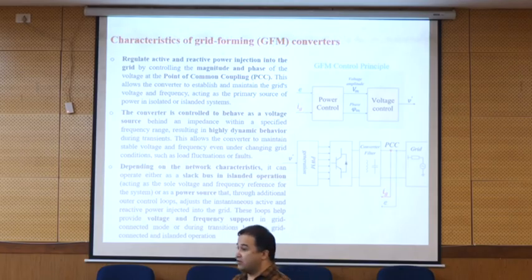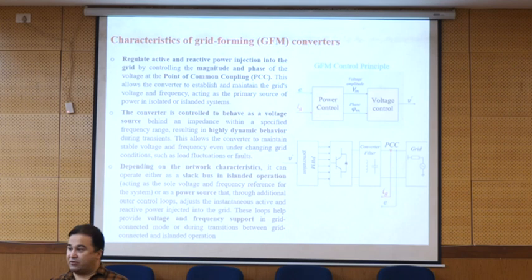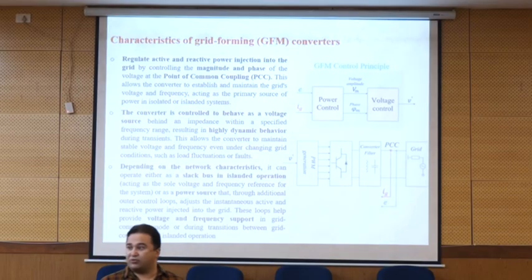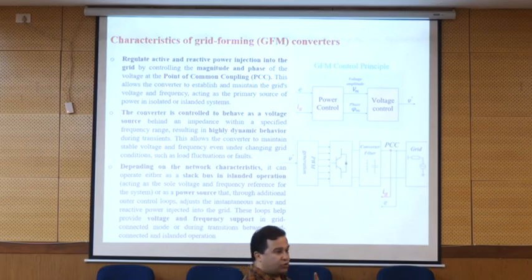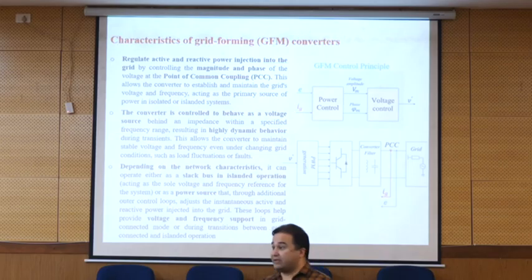Basically any component, it can be a transformer, it can be a converter, it can be anything, but you need to follow the grid code. A simple example: grid code says that you can provide electricity and integrate to the grid if the THD is less than 5%.